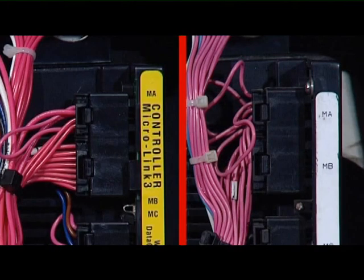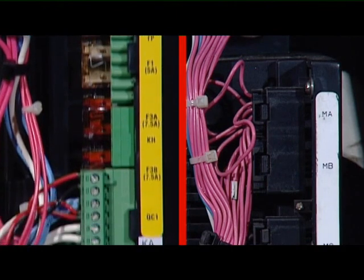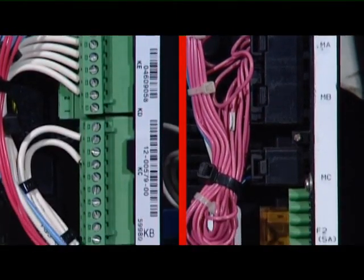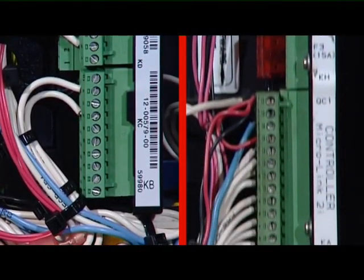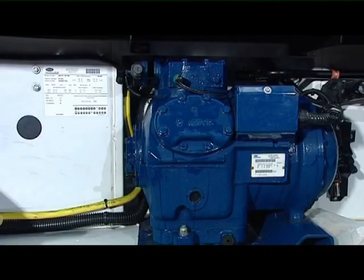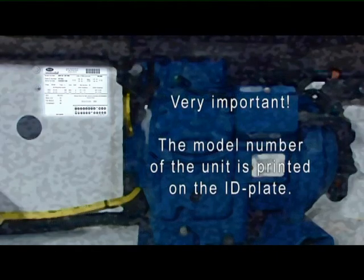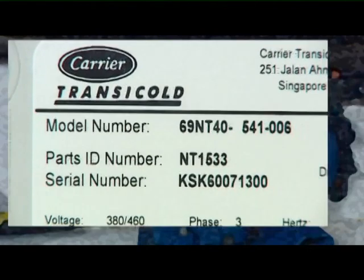The Microlink 3 controller has the step driver motor installed inside, which regulates the opening of the stepper valve, whereas the Microlink 2i unit's driver motor is installed next to the valve in the compressor section. Very important, the model number of the unit is printed on the identification plate.